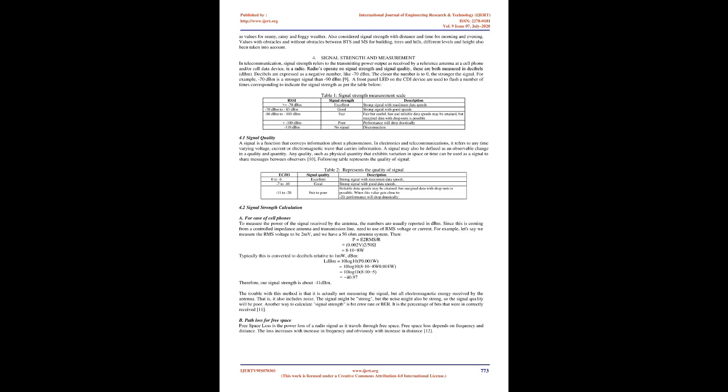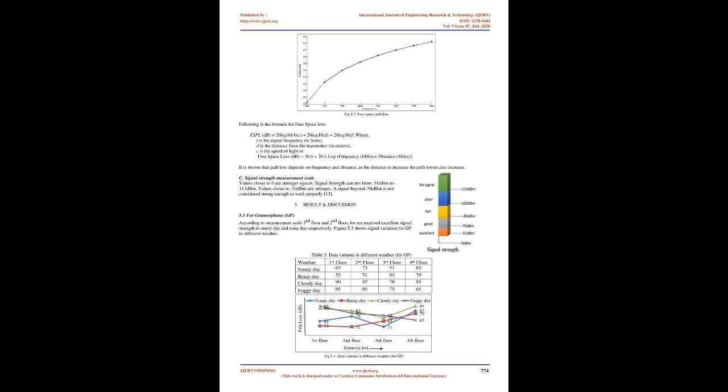Wireless sensor network, WSN, is widely used in fields such as environmental monitoring, industrial site acquisition, intelligent home automation and medical application. Some kinds of commercial devices are designed to support these applications. Received Signal Strength Indicator, RSSI, is regularly used for localization, but the environment factors have much larger effects on the RSSI than distance. As a result, the RSSI is too unpredictable for range estimation. So in a real application of RSSI, calibration should be adopted to reduce the influence of environment.